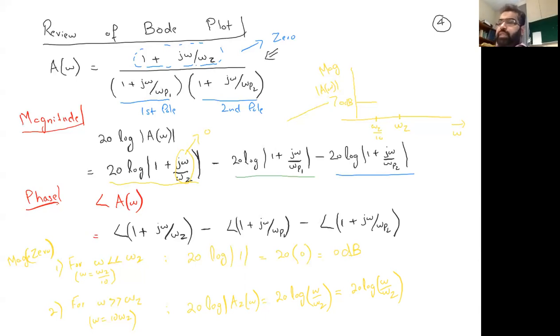And what does this mean? This means I can ignore this omega z factor, and that will be totally depending upon whatever the value coming. So that's why it's going to have a ramp increase all the time onwards from this point, based on the ratio of omega and omega z. So it's 20 dB per decade, and it will have a ramp which is going to be enhanced based on this value. Okay, till here?